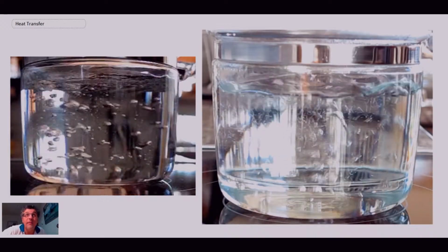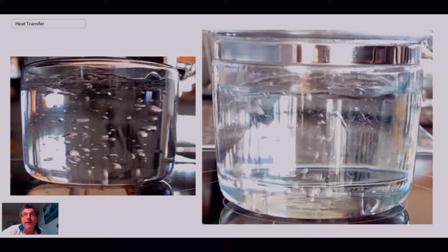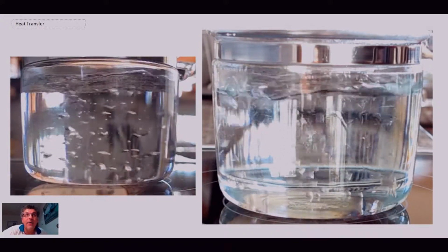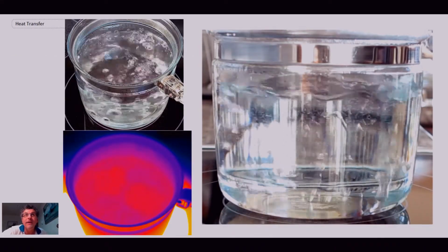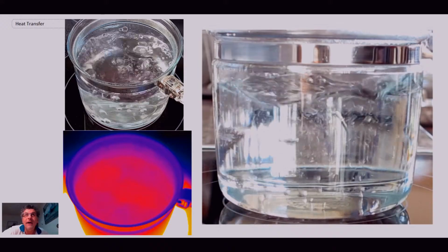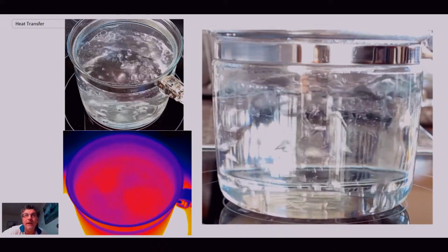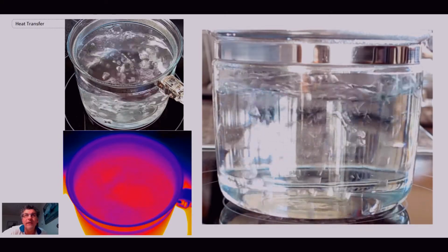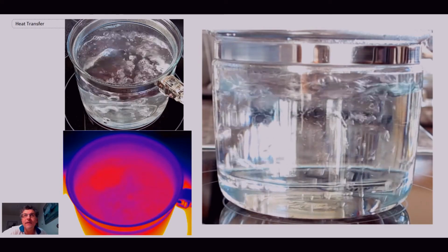And there you can see all the bubbles making it to the surface, vapor coming out. And so that would be full boiling taking place, saturated pool boiling. Prior to that it was subcooled because we weren't at a high enough temperature. And there you can see the IR camera. As the bubbles come to the surface, we get pockets of very hot fluid, and that's the more yellow temperature in the red mix that we're looking at. And so that is a video describing boiling.